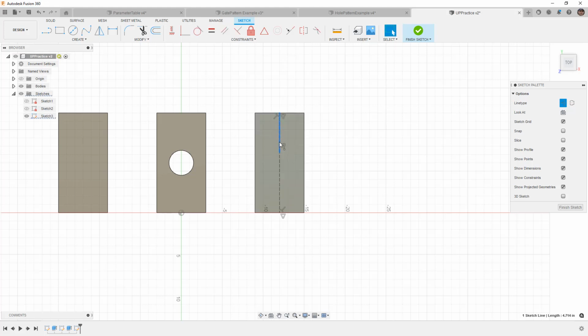One way is for us to make both of these lines equal in length, which will always find the center of that face. Another is for us to use another construction line. Find the midpoint, find the intersection, then we're going to make these two perpendicular.